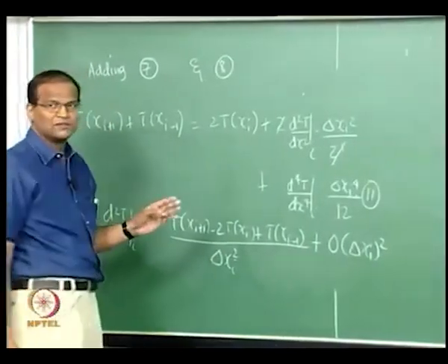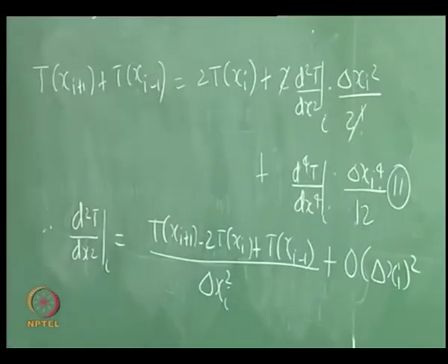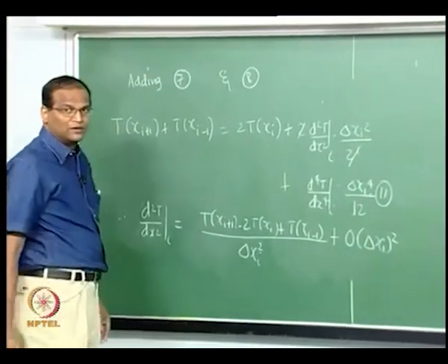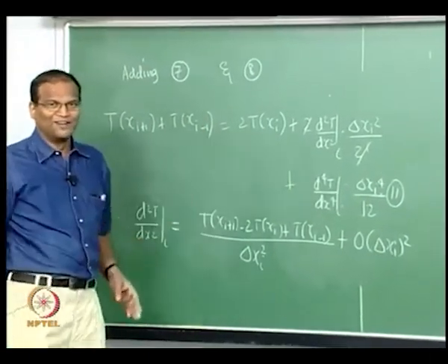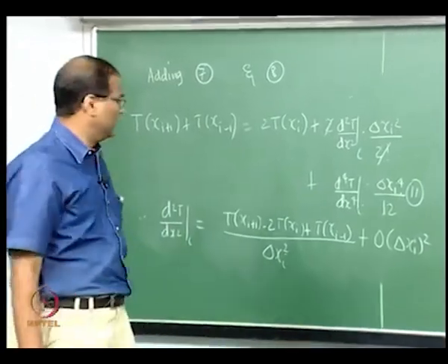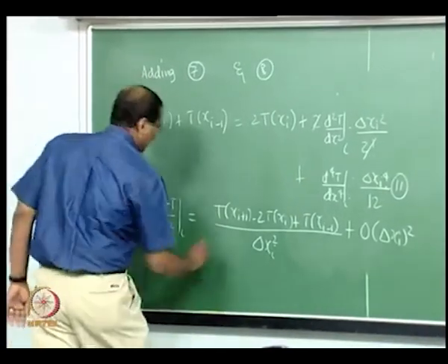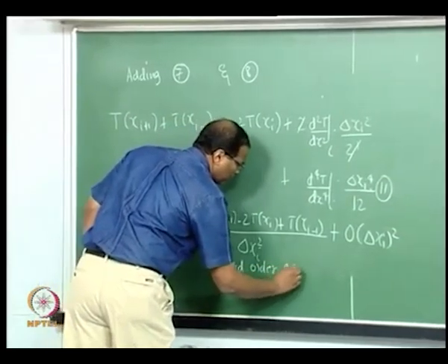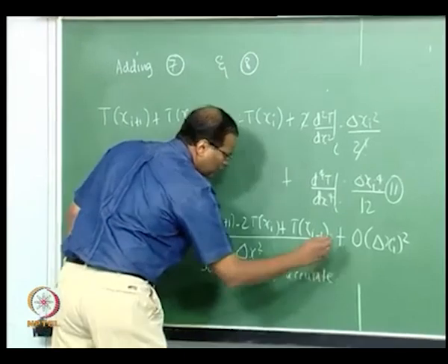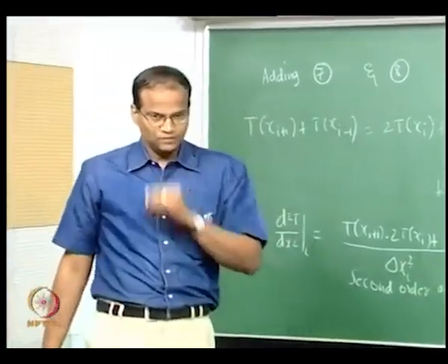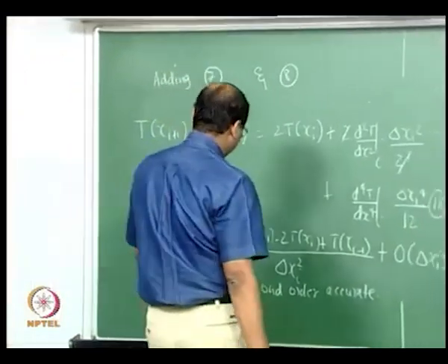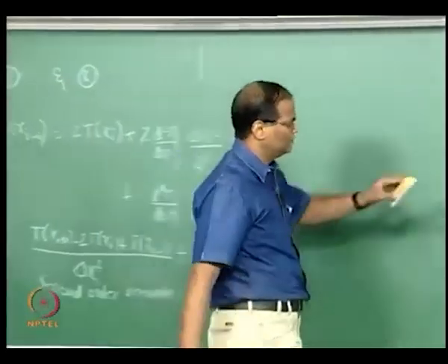Okay, this is central difference, not forward difference. This is called the central difference. I plus 1, I minus 1, everything is there. What is the forward here? You got forward and backward. It's for an elliptic equation, right? It's for elliptic. So this is basically second order accurate. So now we got an expression for d square T by dx squared.